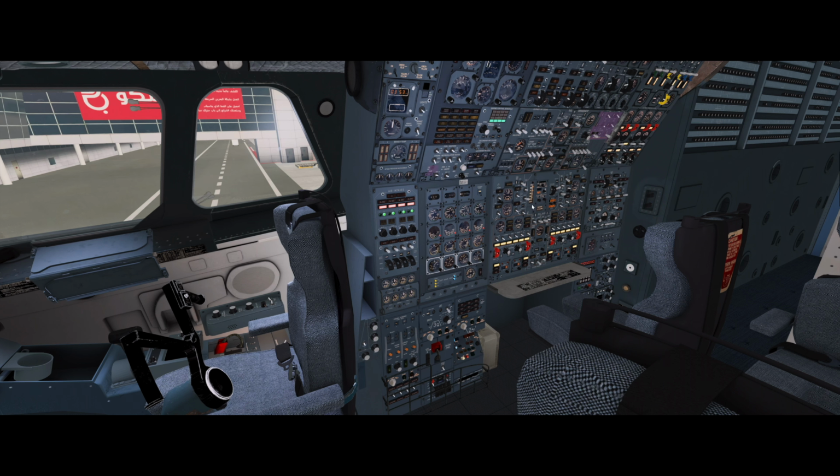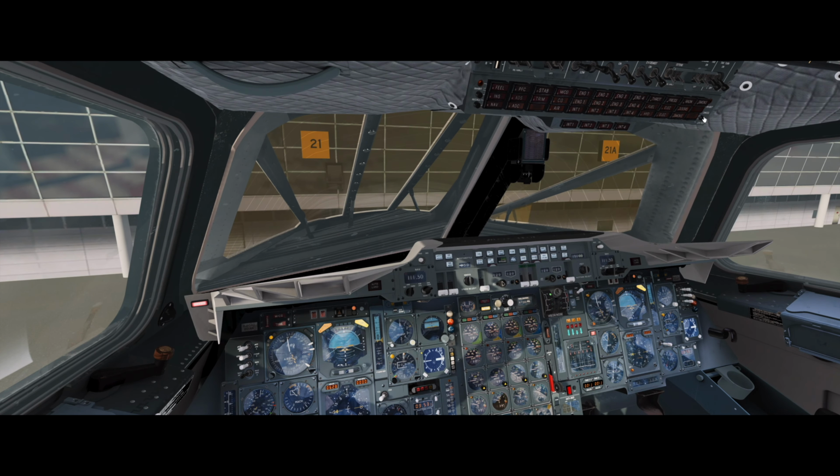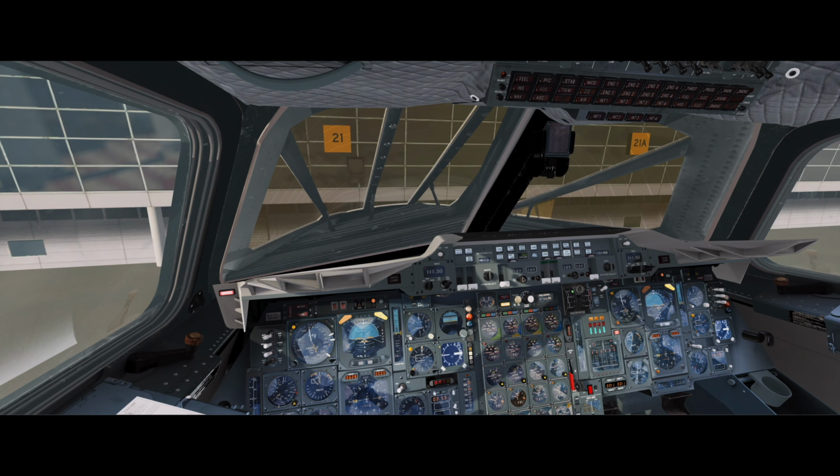1, 75, 0, 56. Checked. Load limits. They are set for a transfer. Start clearance we've got. Door lights. All out. Master warning. Has been recalled and checked. Anti-collision lights. On. Throttles. Idle. Engine feed pumps. They are on.